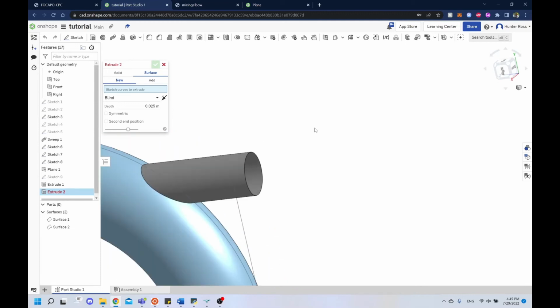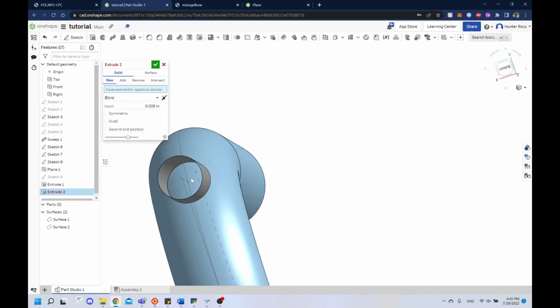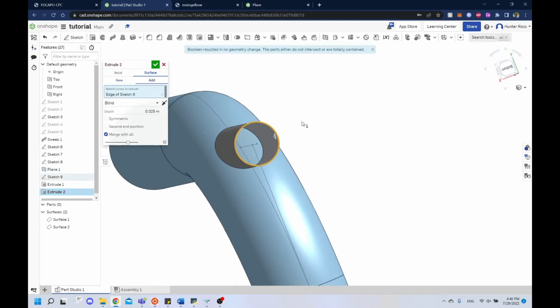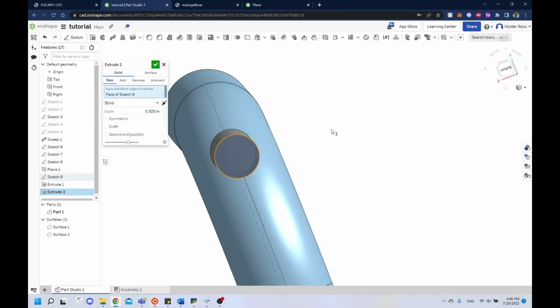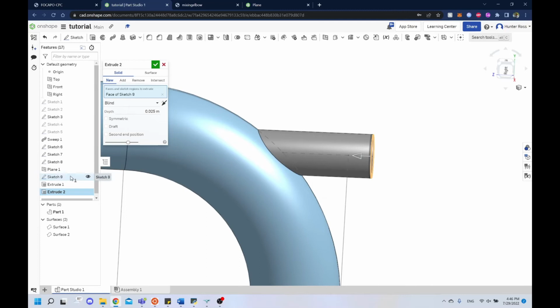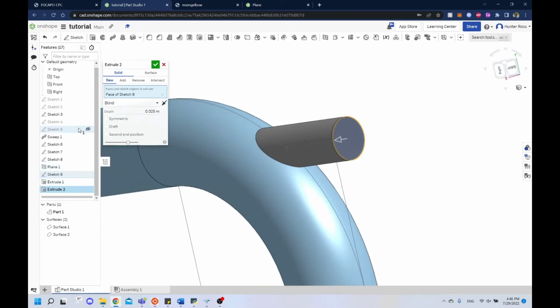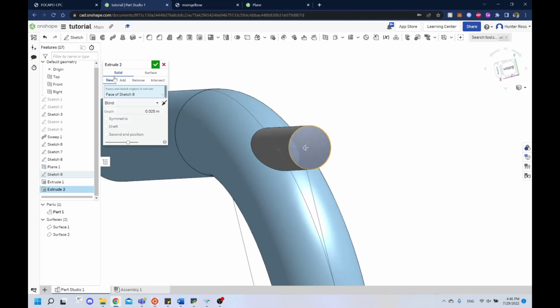What extruding does is make a sketch into a volume, right? And actually, we can't do it. Oh, we could actually, if we chose the sketch here, chose a face here. You'll notice that the sketch went away, because when you extrude or sweep something, it will make the sketch disappear. But you can always tell it to come back by clicking this eye. We say make a new solid, and let's just give it some depth. Let's say 0.75. Let's see, will that go through the other side?